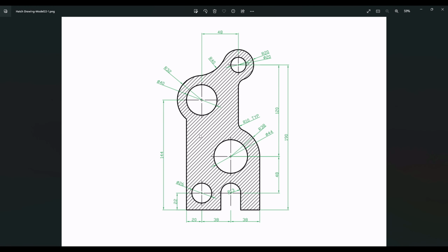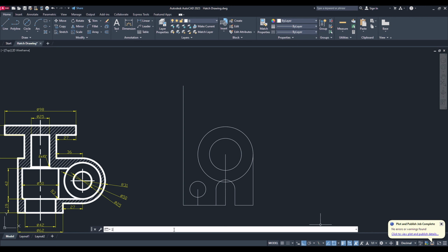After that, from this bottom to this center point of the circle, I can see it is 144 height. But what if I want to go from this point to this point? Simply minus 22 mm from 144. So you can easily go from this point to this point. So it will be 122. So take the line command. So start from the center point and provide 122.